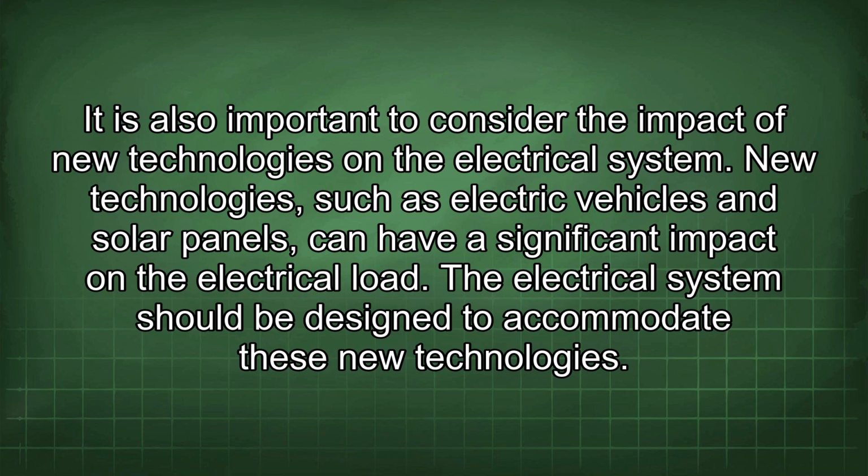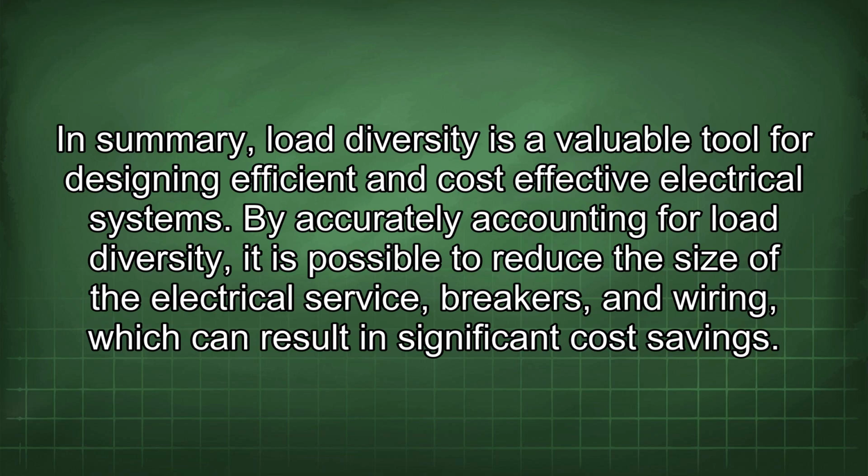It is also important to consider the impact of new technologies on the electrical system. New technologies, such as electric vehicles and solar panels, can have a significant impact on the electrical load. The electrical system should be designed to accommodate these new technologies. In summary, load diversity is a valuable tool for designing efficient and cost-effective electrical systems. By accurately accounting for load diversity, it is possible to reduce the size of the electrical service, breakers, and wiring, which can result in significant cost savings.